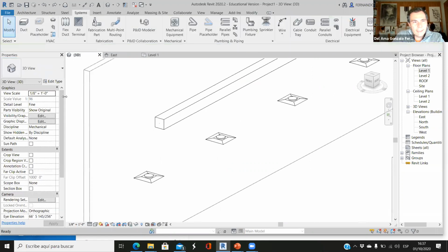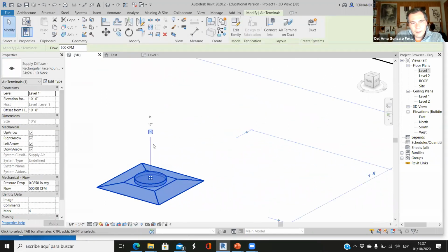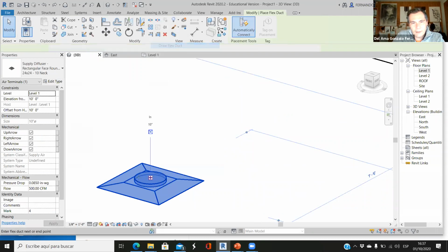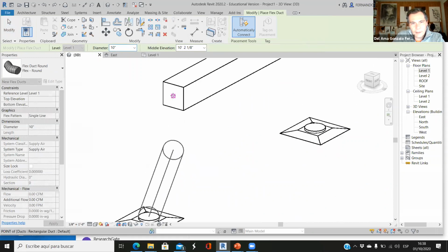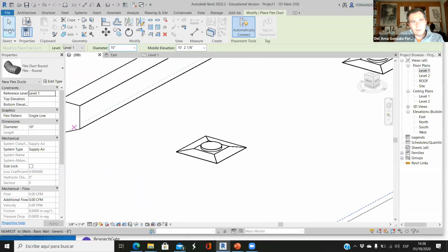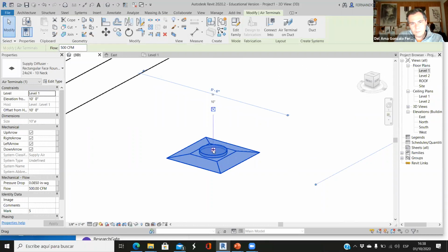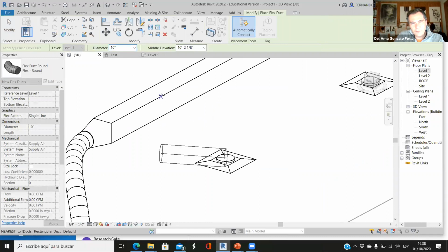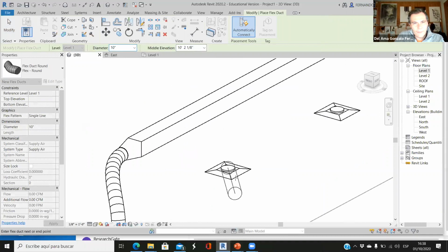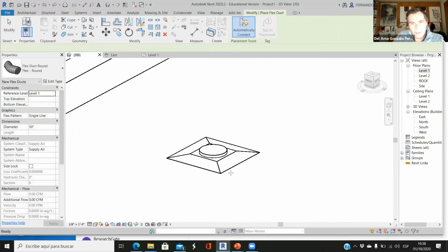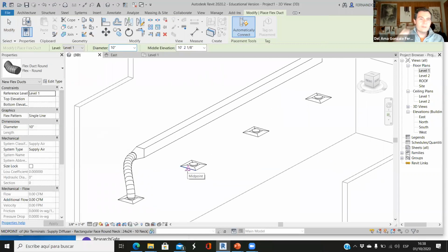What if I select this and I right click here, I create the flexible duct, and I try to connect this to the duct itself? Well, now it works. Okay, what if I try to do it with this duct here? Flexible duct. I need to find the axis, so I don't think, no, terrible. Okay, so if Revit doesn't like this way, I have to try something different.